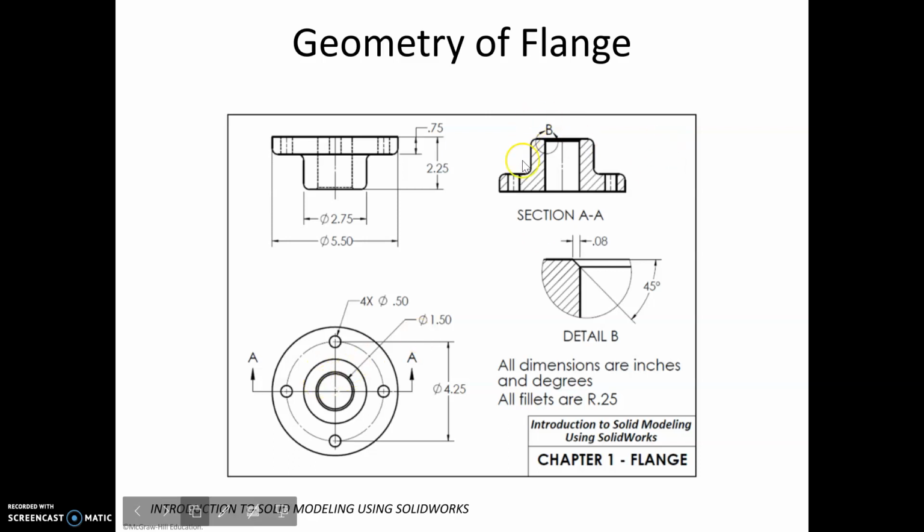We can tell it's in the middle because we can look at the section view, and a section view is when they cut away part of the model. So you see this A-A line here. This is what's called a section line. Basically you're dropping a buzzsaw right through that part of the model, and you're looking at what it looks like on the inside.